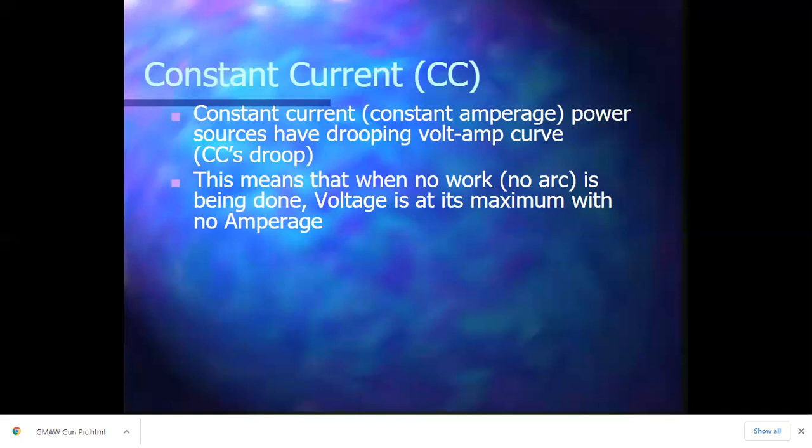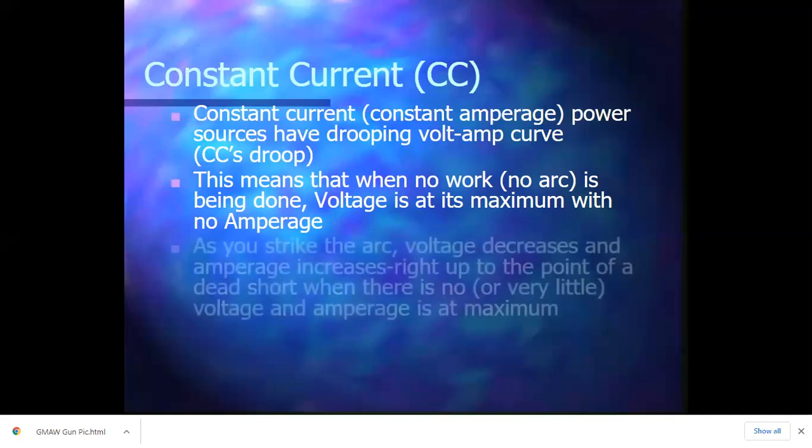When we get into class, we get into the shielded metal arc welding unit, I'll show you this on one of our machines. Our open circuit voltage is generally 71 to 72 volts. And that's sitting there, just waiting to go, waiting to be activated. And then you touch that rod to the plate. Amps are always going to be there, and the voltage will spike up and down. That depends on arc length, how close you keep it, how much resistance is in the arc. And we can do some fun little experiments in class, and I could show you that by keeping a nice close tight arc and opening up a big arc, creating a lot of resistance through the air, stuff like that. It's pretty neat.